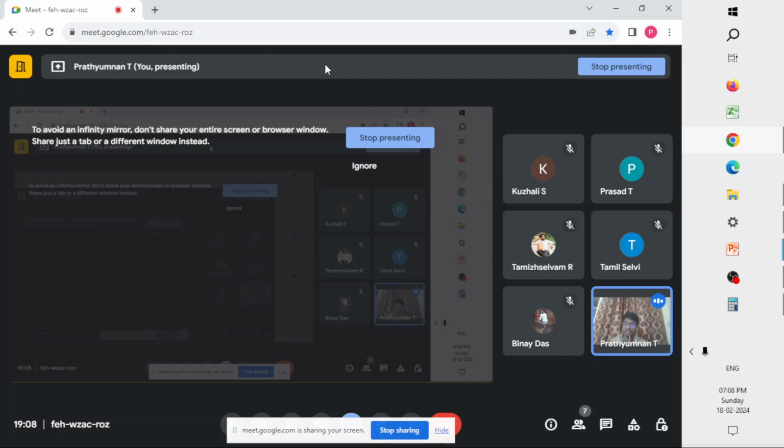Because those are quite tedious calculations also, and there are many terms for which you actually need to know the meaning, like Rayleigh number, what is Rayleigh number, what is Nusselt number. It's just given the expression is hL by k or h into delta T or delta C1 C2 by k, but what it actually means, what is the meaning of the Nusselt number?